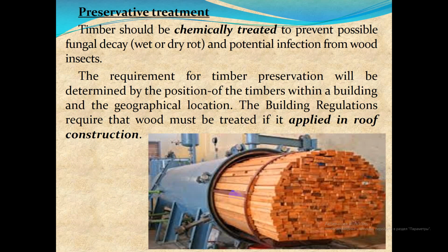Preservative treatment. The majority of softwood contains a high proportion of sapwood, which is essentially the growing layer of a tree. This is more prone to attack than the denser structural hardwood found closer to the core of a timber trunk.